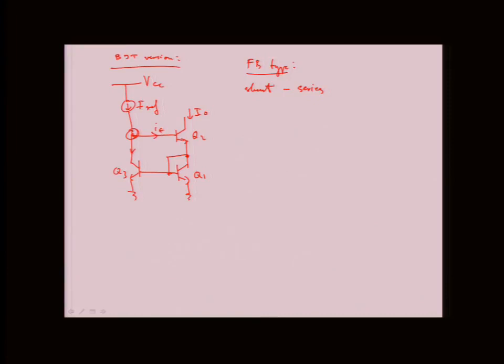Okay. So how does the small signal model look like here? Let's do R out. The sources are 0 is what? So what we see from here, still we get RO2, and then plus we have 1 over GM1 in parallel with RPi3, which we can kind of neglect, so it's approximately RO2.